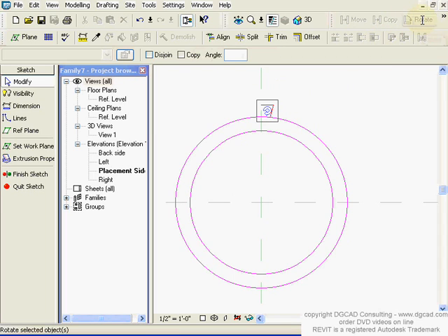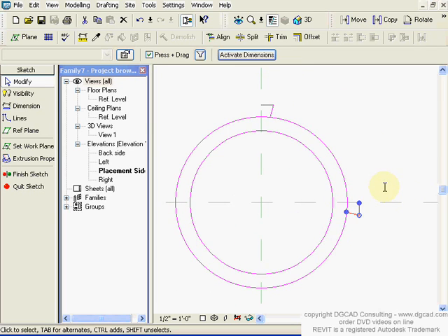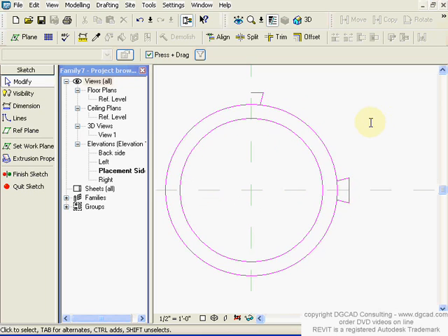And I'm going to hit rotate. Okay, and I'm going to put my copy on, and I'm going to read my command line, and it says down there, or drag rotation center control. So this is all about really just trying to do a rotation, and I'm going to say from here to there, more or less like an array. I want to get it exact, so I'm going to click on there and go in here and hit mirror and mirror that about there.